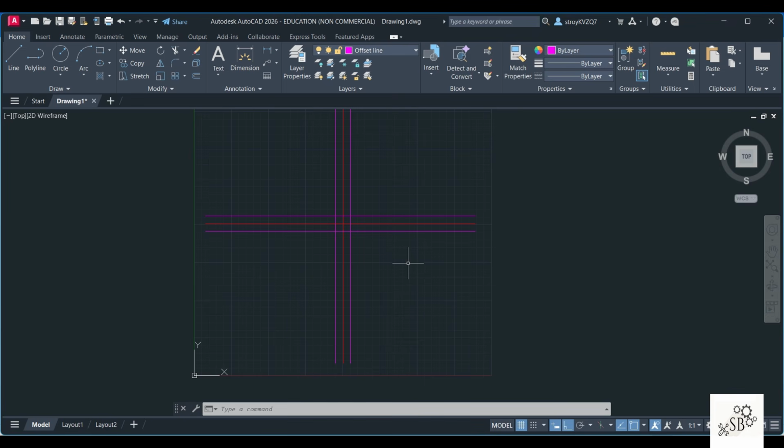projection. In first angle method of projection, we generally draw the front view, the place where I'm indicating. Top view is always below the front view. And for drawing the left hand side view, we choose the right portion, that is over here. So front view will come here. This side will be your left hand side view. Here will be your top view.